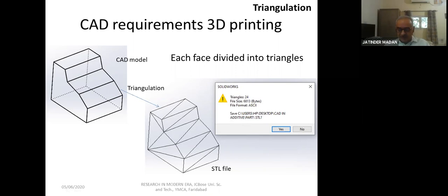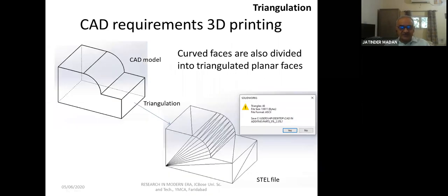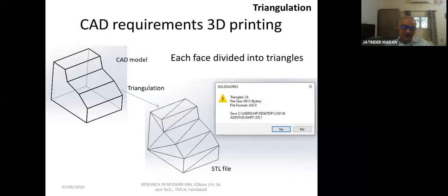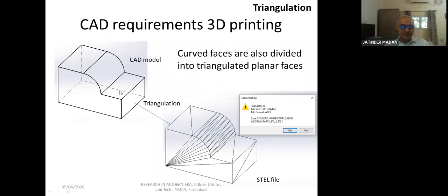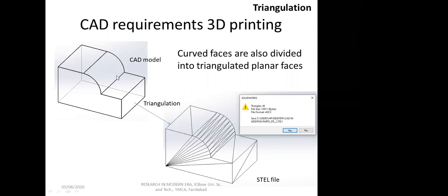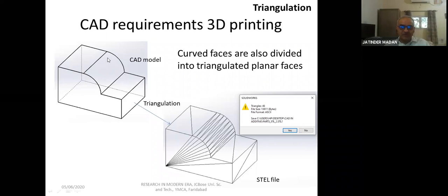Okay, and once you have the other models, you see all surfaces are flat, so you need not worry. It is perfectly representing the same CAD model because everything is represented well. Because I told you that once you have flat surfaces, the approximation is perfect. The moment you make a curved surface instead of a flat one, you need a larger number of triangles or smaller triangles.